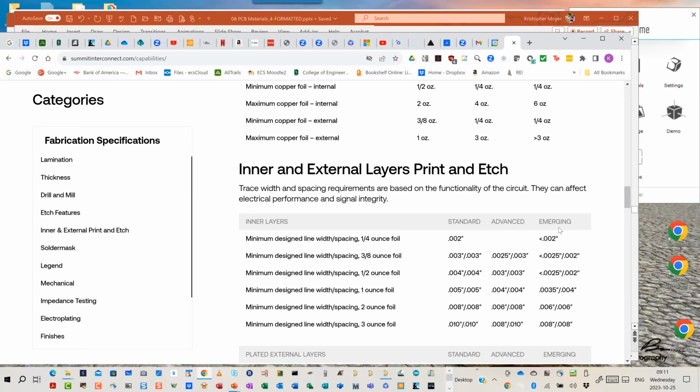Basically, there's going to be a set cost that they have to produce that panel. Maybe it's like $3,500 or $5,000, whatever it is. Let's go 5,000. The math is easier. If you design your board in such a way that because you made it just a hair too large that they can only get one image on that panel, you're paying $5,000 a board because you're paying $5,000 a panel. If I can get 2 images of that board on the panel, because I shrink the board size a little bit and they can rotate 90, you get 2 of them next to each other on that panel, each board costs me $2,500. I still paid $5,000 for the panel, but I got 2 boards on the panel, so each board is $2,500 and so on.